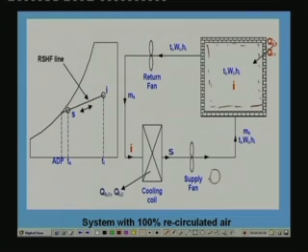That means Qs R should be equal to supply airflow rate into CPM, that is the specific heat of the humid air, into Ti minus Ts. Okay, this is the energy balance for the sensible heat portion.